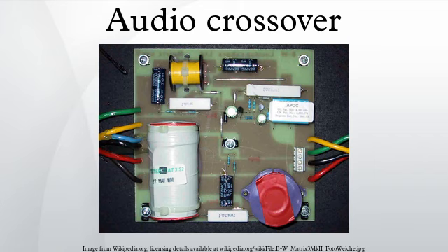Their behavior changes with the signal-level-dependent dynamics of the drivers. They block the power amplifier from taking maximum control over the voice coil motion. They are a waste of time, if accuracy of reproduction is the goal. Alternatively, passive components can be utilized to construct filter circuits before the amplifier. This is called passive line-level crossover.